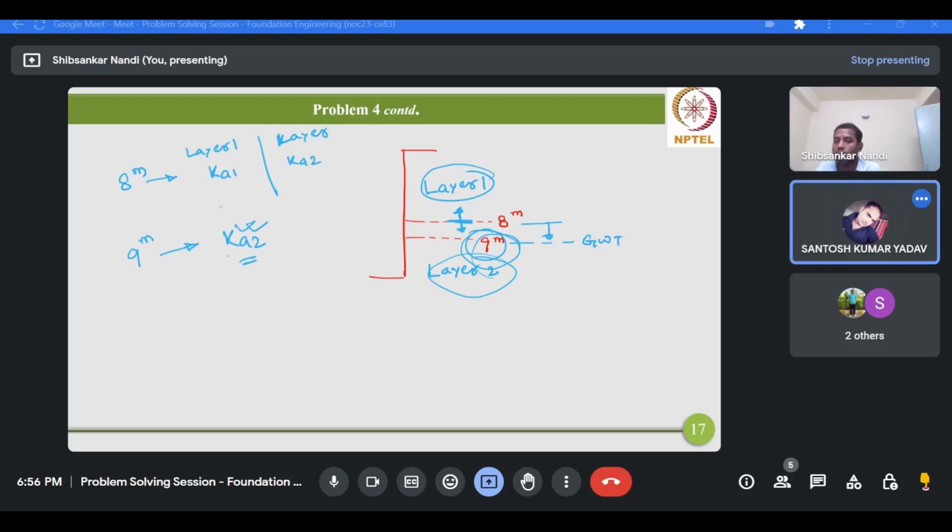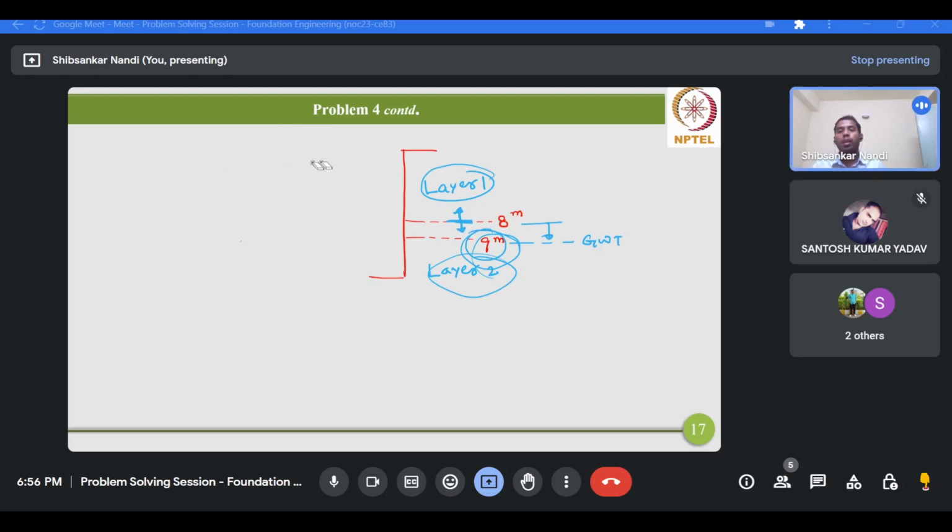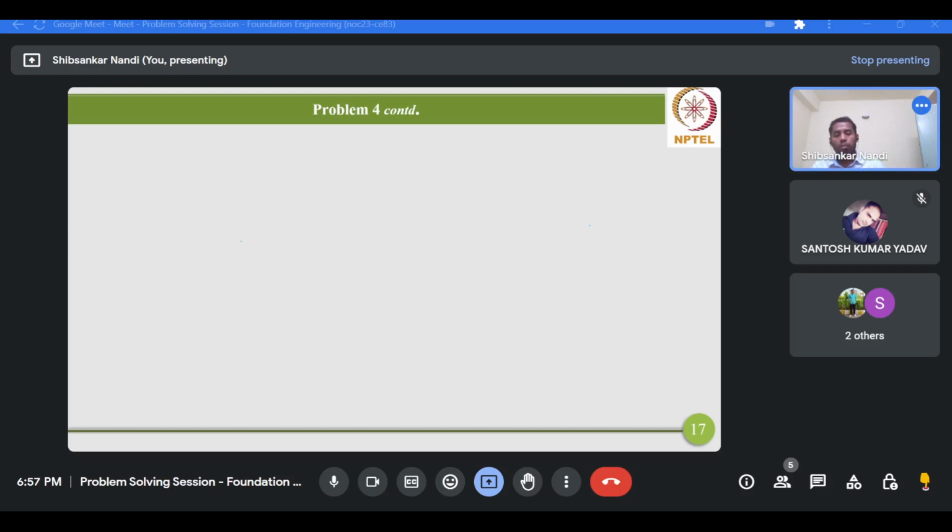Okay. Now we'll add the previous PA components, and we'll calculate the total lateral active force behind the wall after the formation of the tension crack.